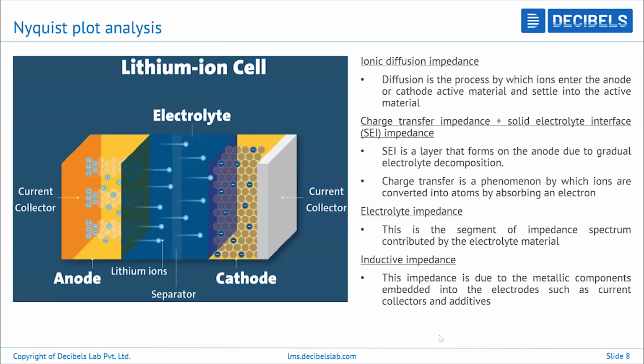So that is why we are validating EIS as a very detailed and a much more preferable method. This is why it's able to give the condition of all these different components: the cathode, the anode, the electrolyte, the solid electrolyte interface, the inductive components, the condition of the electrodes and the electrolyte. So this is what this EIS testing is able to reveal. Okay.